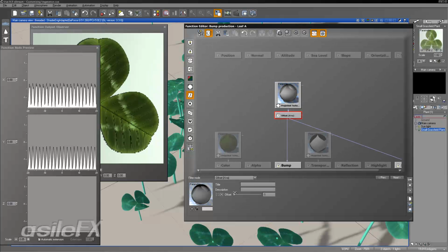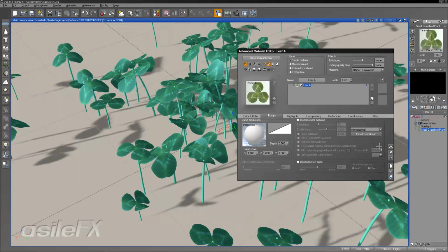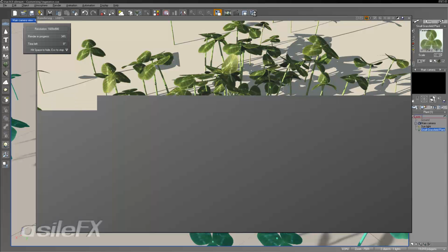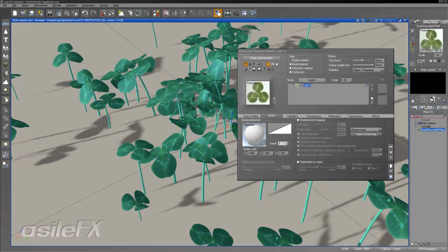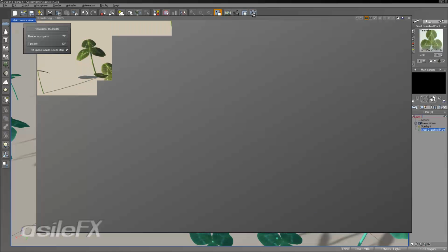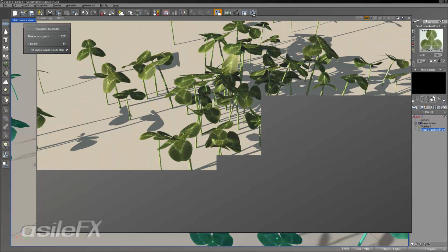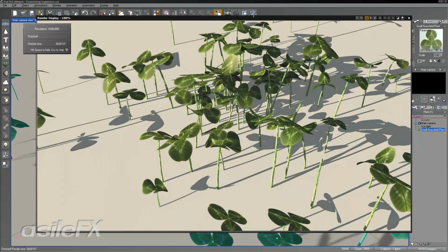So when we offset in a specific direction, we're controlling the bump. As long as we're below 0 or above 0, the bump is going entirely in one direction. So there's no in and out variation. That can be pretty helpful for putting texture maps on leaves, and we'll go ahead and try something reversed. Try -0.2. And that works pretty well.